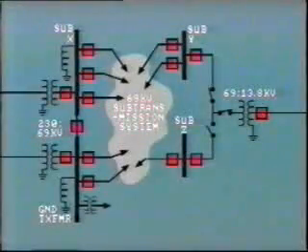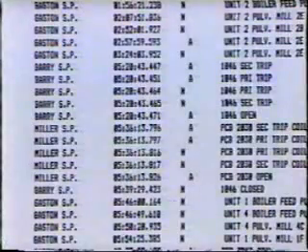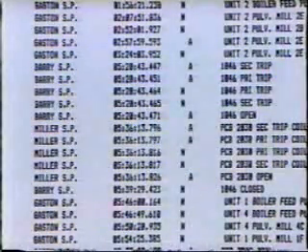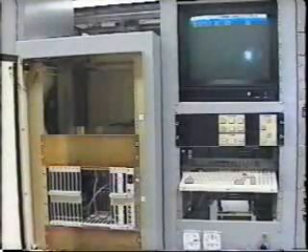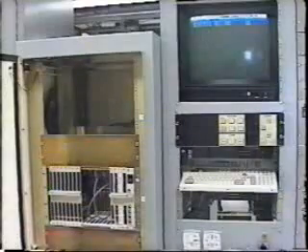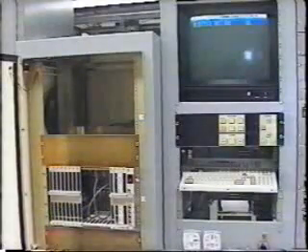By correlating the one-line diagram with the oscillograph traces, we can usually reconstruct what happened and consequently analyze the fault. We may then verify our findings by checking the printout from a sequence of events recorder, also known as an SER. The SER may be an integral part of the oscillograph system, but quite often it is a standalone machine.